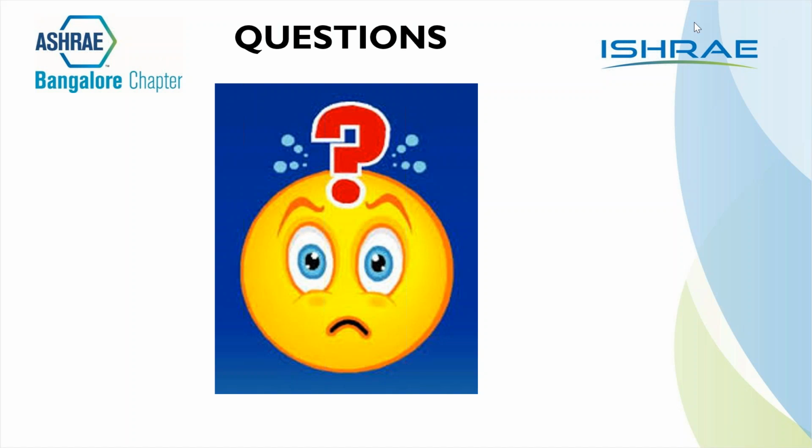My next question, from another party, is, if all VRF indoor units serve constant load applications like UPS or server rooms, can diversity be considered or not? I have answered this question in my presentation itself. Because of the ambient conditions, no, you cannot consider any diversity, but you will have power saving. Next question is, in a VRF system, can the intelligent monitor be connected with a centralized BMS system?